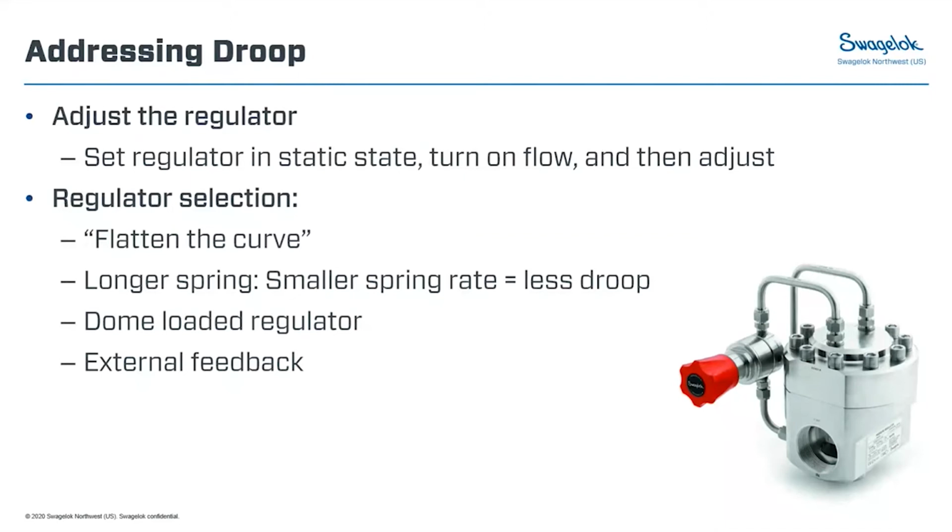We do say that we should not use that as a relief device, but it's more so eliminating the need for a vent valve downstream. But again, if we do have that venting option with the regulator, we want to also consider a relief valve in the system. But yeah, great question.